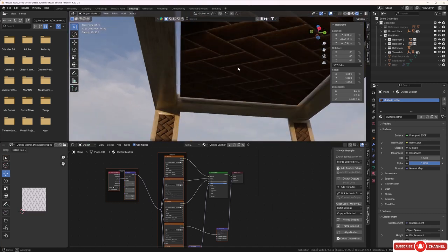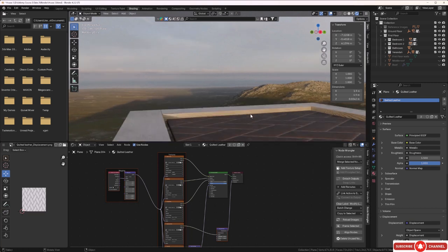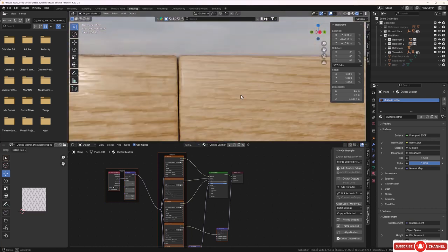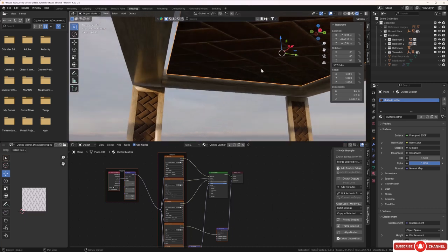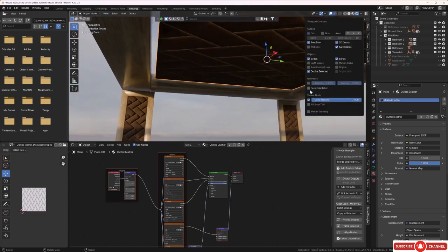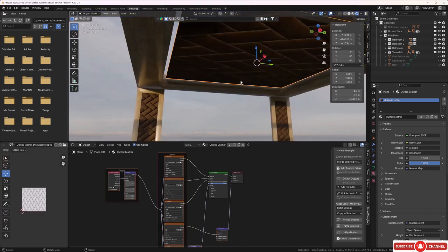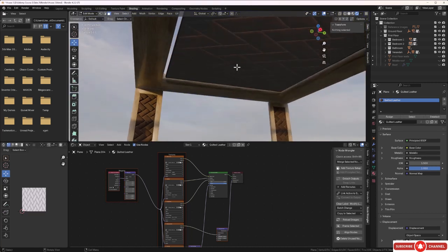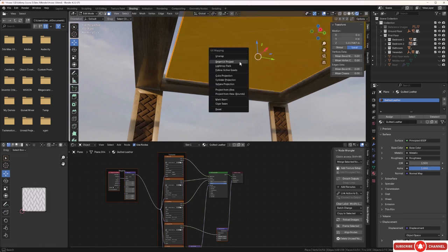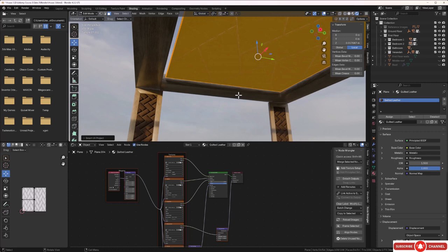So let's check maybe the normals on this one too, or let's just go ahead and do it. Let's just try that. So we'll hit the little drop down and hit face orientation, and no, that's all good in this case. So I'll turn face orientation off. We'll tap into edit mode and we'll just try a UV map on it. So we'll press A and we'll press U and we'll go for Smart UV Project and unlock, and there we go. Let's grab everything in the UV map here and hit S, and we'll try to scale this down a little bit like this.